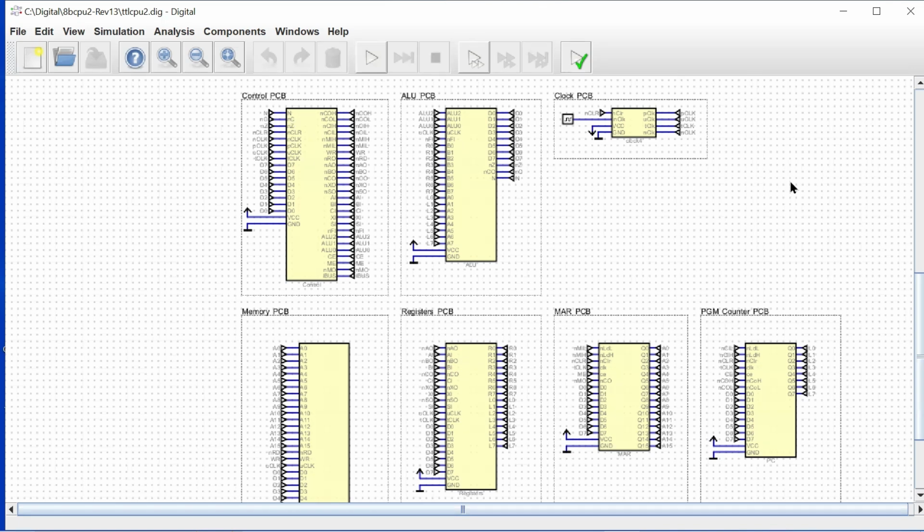I made the decision that each card's level interface is going to be potentially unique. The main driver there was that, since I would have a smaller number of controls per card, the routing on that individual card would be simplified. I wanted to go that way because the card level design was just a big unknown to me.